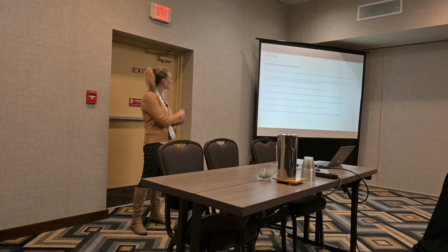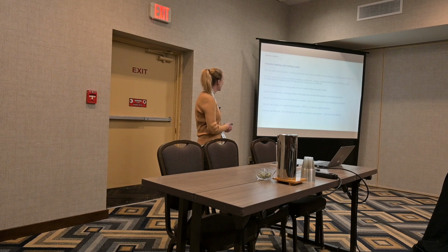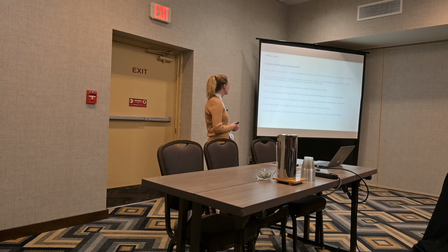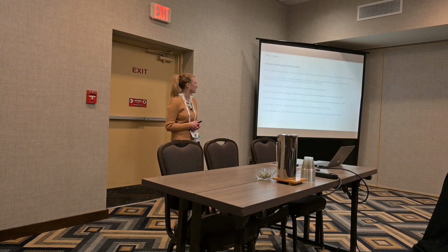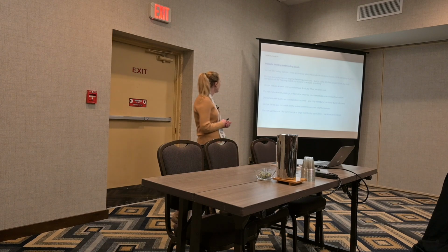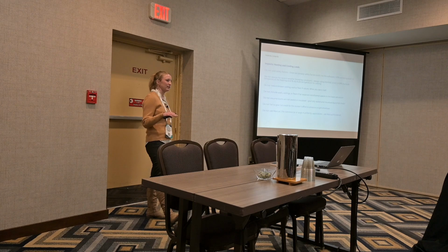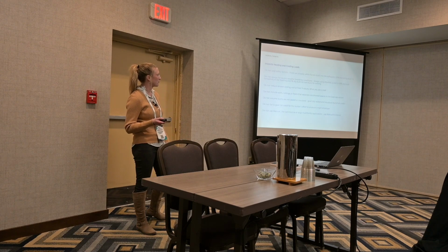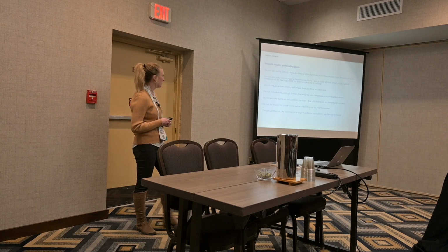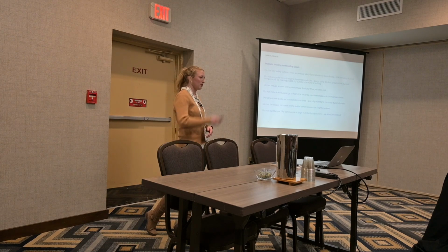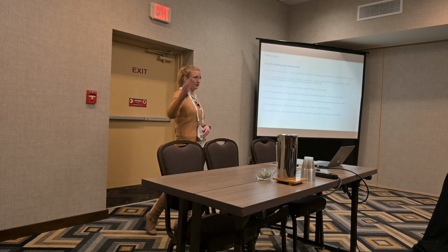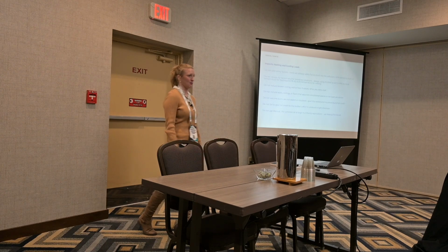All right. Do not design for record weather breaking conditions. Like we talked about, use the ACCA or ASHRAE 99% dry bulb temperature for heating and 1% dry bulb temperature for cooling. Do not reduce known ceiling, wall, or floor R values. What you see is real in the home. Do not include walls, ceilings, or floors that separate conditioned spaces in the load calculation. So if you have a floor or a wall and there's conditioned space on either side, you're not going to put that in the model.